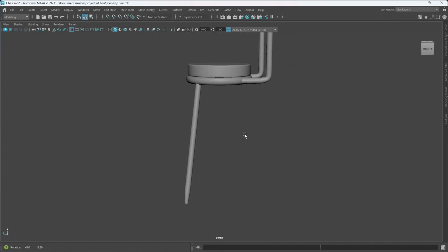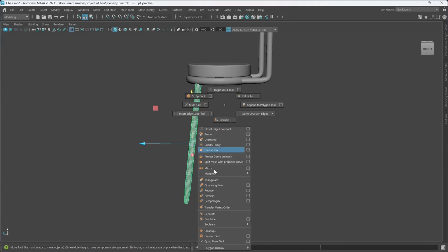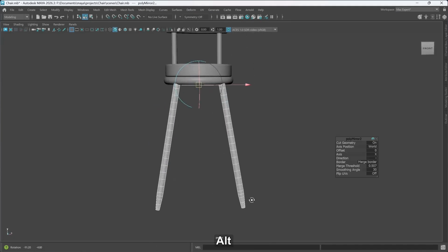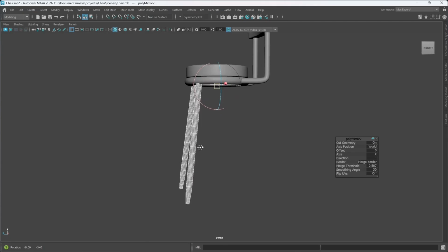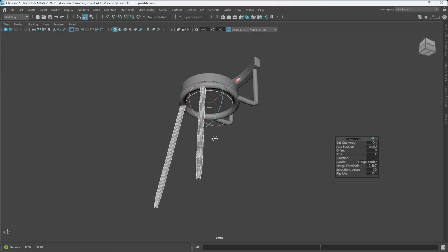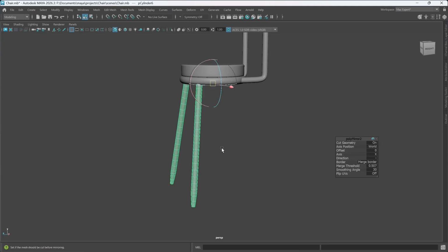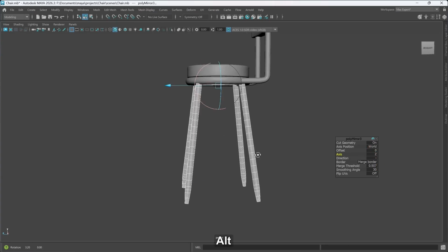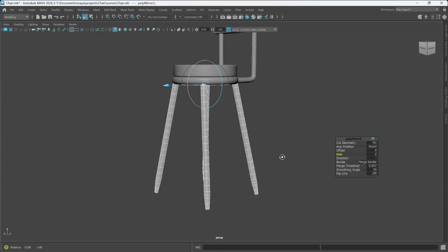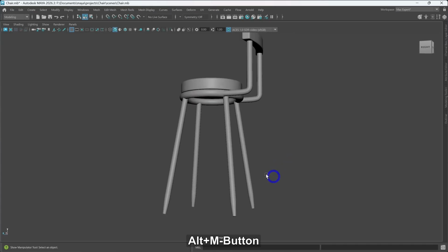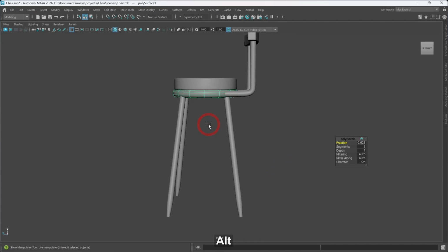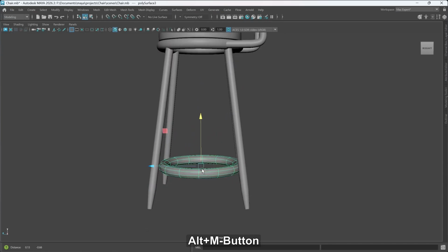Okay, what we are going to do now is to select this, shift right click, and mirror this. Of course, we want to mirror it to the x-axis for now. That is looking good. Then we'll click off, select again, hit on G to repeat the mirror, and this time we're going to mirror to the Z axis, and this is also looking good. All right, this is fine.